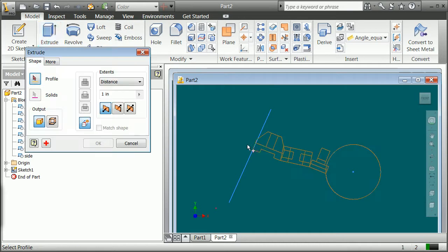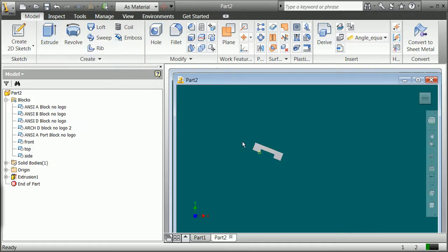You can actually now go into this. Let's say that was your part. You're going to go ahead and push that one out 5, 4, and you see that we do have some sort of part there. So how you manage sketch blocks is something that's definitely worth playing around with, but right now I just want you to see how important it is to make blocks. And then in this case, you might not have wanted to put things on layer 0 for the blocks, though that is our general fundamental rule.